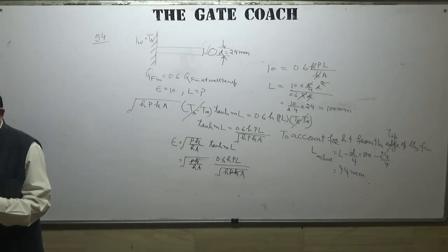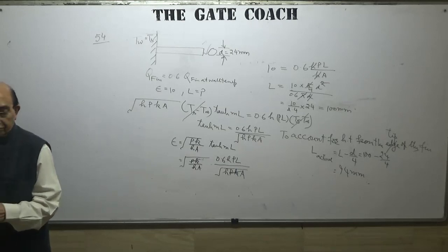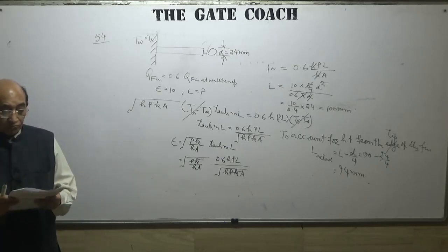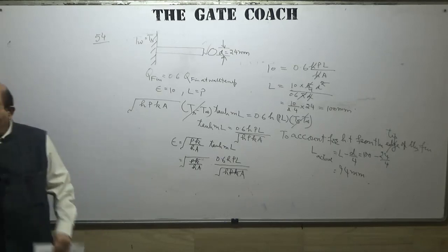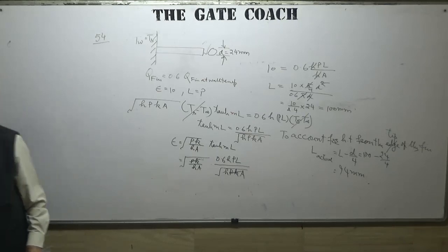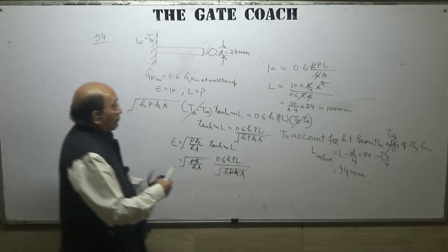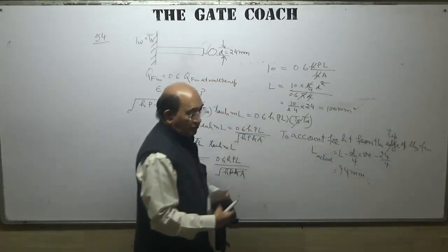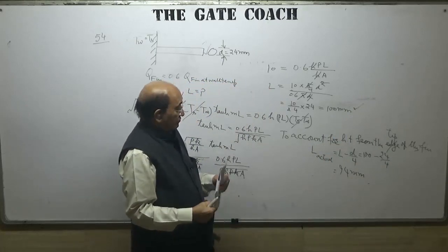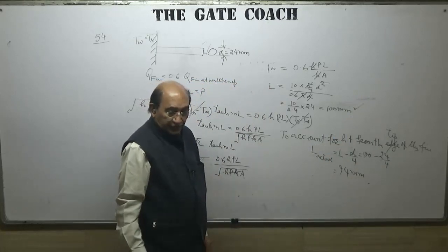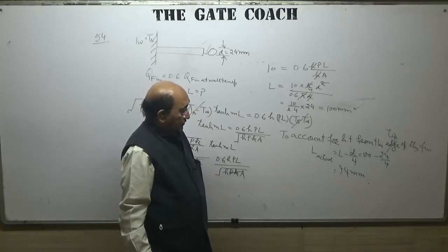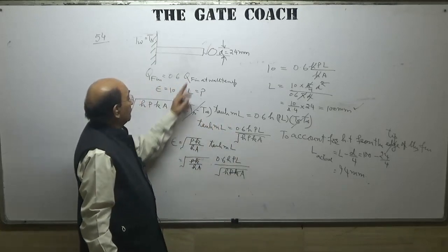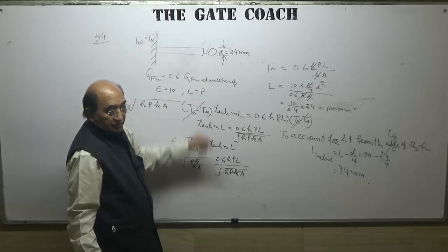Thus, the answer given is 94. Most of the students may write this, but those who have done some problems on the design of the parameters for the fin must have noticed that this equation was when the tip of the fin is insulated.